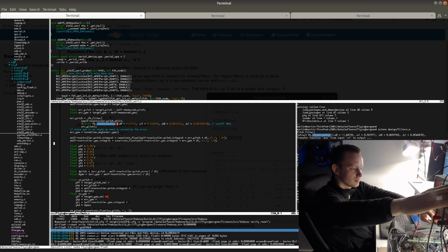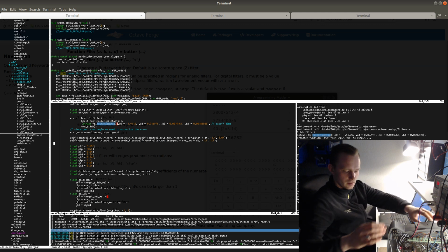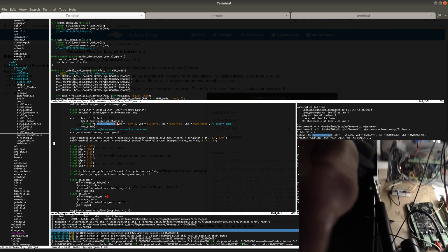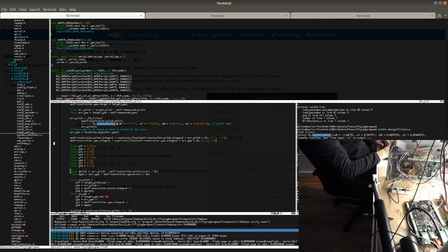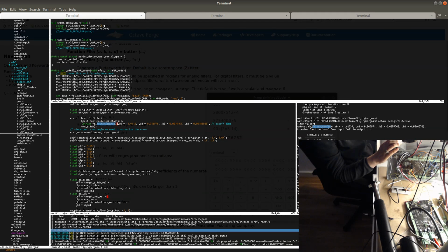And then I can power on the motors. And let's see here. So what I'll do is just excite this system using the joystick, and this is going to be without running the controller. This is just going to be open loop excitation of the system, and I'll record the data here. I'm going to start this run test, and then I'm just going to excite the system. So let's see.